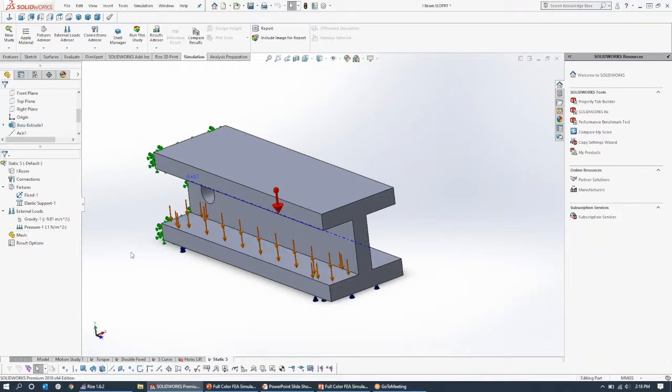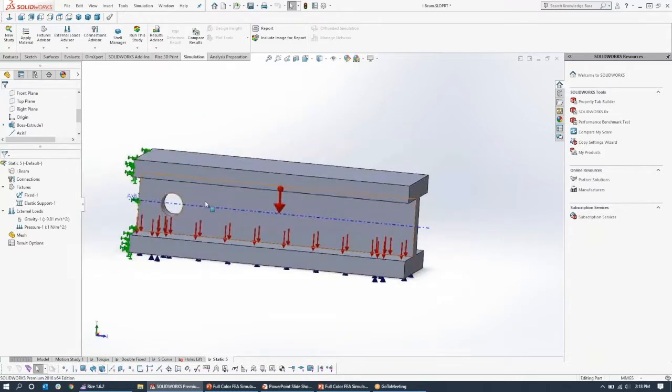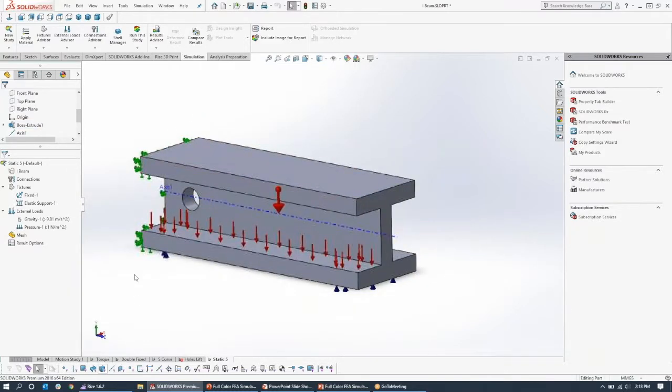In some cases, such as the generatively designed part that was shown on a few slides previously, if you have a complex part like that, then it may be helpful to reduce the resolution of the mesh. I know that my computer struggled to run the simulation and failed several times because the process just couldn't handle the amount of complexity on a part that large, complex, broken into so many pieces.